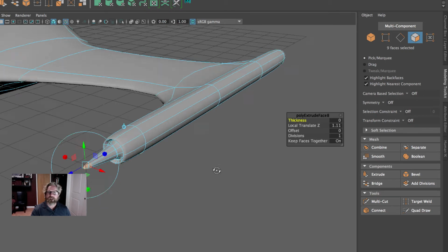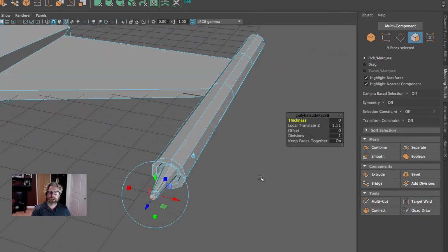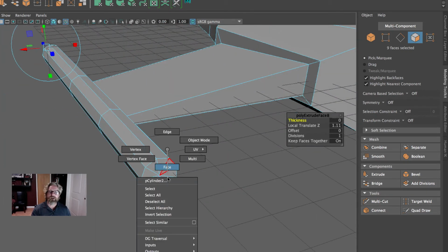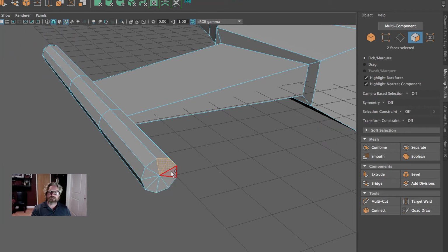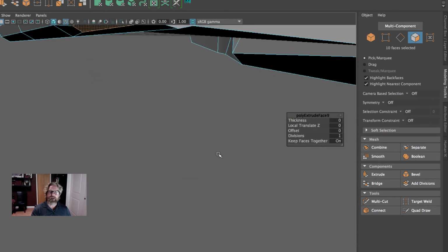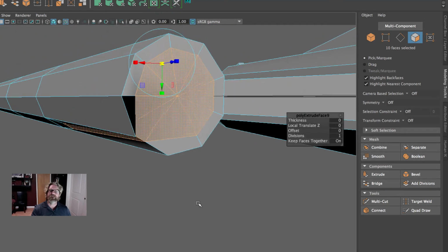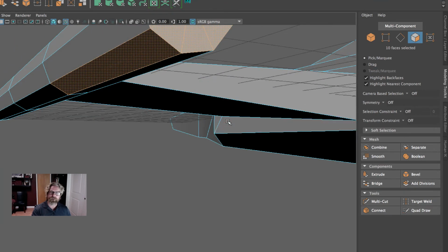And we can hit the 3 key to see how that will smooth out very quickly. Do the same on the back. We'll just give it a little exhaust. Extrude, click the cube, scale it in. Oops, now I've made a bad selection here. I inadvertently selected that one, so we'll just hit undo.